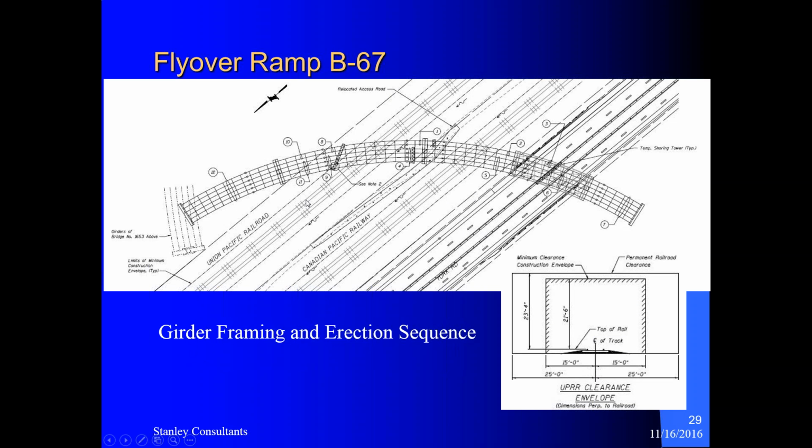And it's also a good idea to come up with a girder framing and erection plan showing the erection sequence. Usually you want to start at the fixed bearing. In this case, this is the fixed pier, and you put the outside girders first, and first you want to stabilize the outside girders. That requires extending them over a minimum of 2 piers, the fixed pier and the next expansion pier, and then from there on you can start erecting the interior girders inward.